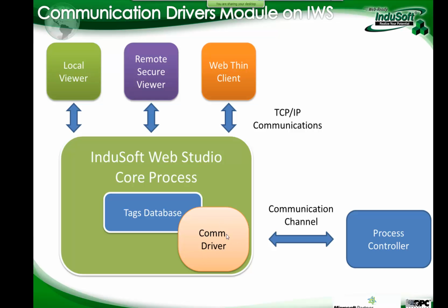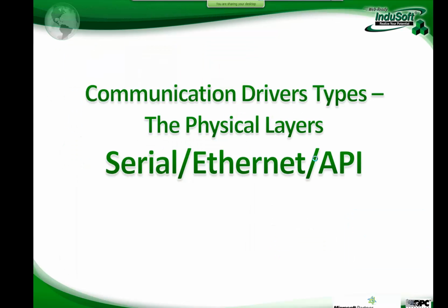So our communication driver would talk to the controller, to the PLC, to the, let's say, multi-loop controller, and we're gonna refresh the tags database, and from the tags database we're gonna go to the other tasks. Usually the viewer or a remote secure viewer, that's gonna be through TCP/IP communications.